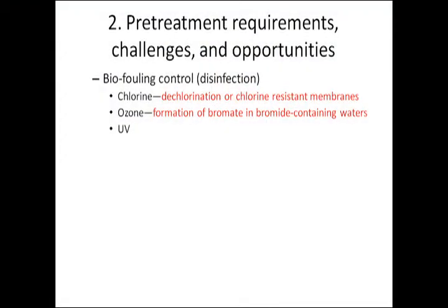Pretreatment represents some very interesting challenges and perhaps some opportunities. We have to worry about biofouling control on the membranes, and oftentimes we do that by chlorine disinfection. If we do that, we either have to dechlorinate after we chlorinate, or else we have to develop some chlorine-resistant membranes, and I think there are definitely some opportunities for improvement in that regard.